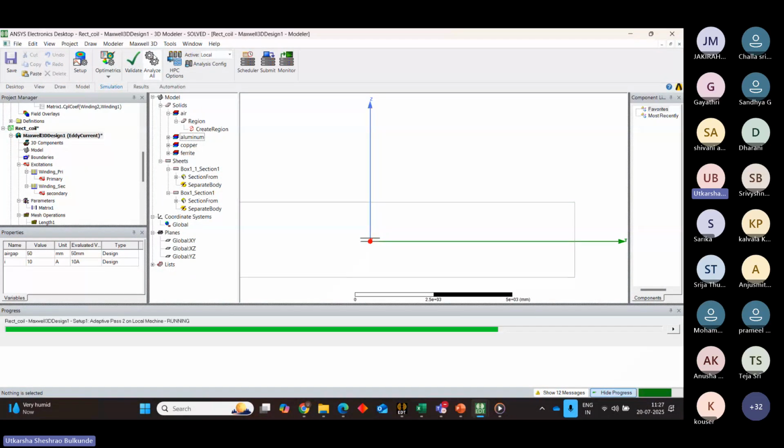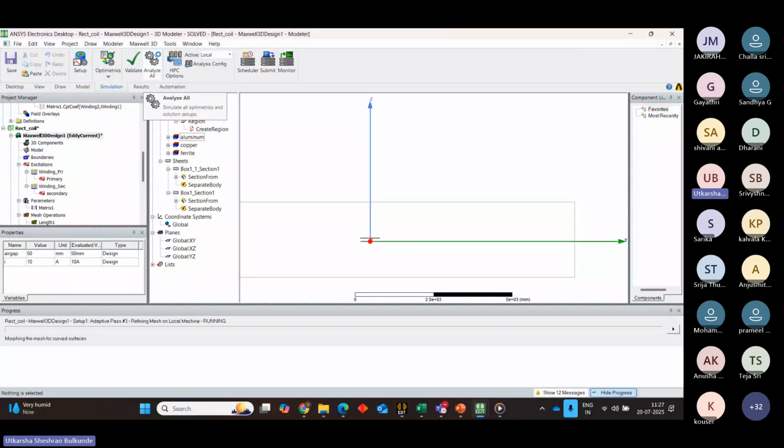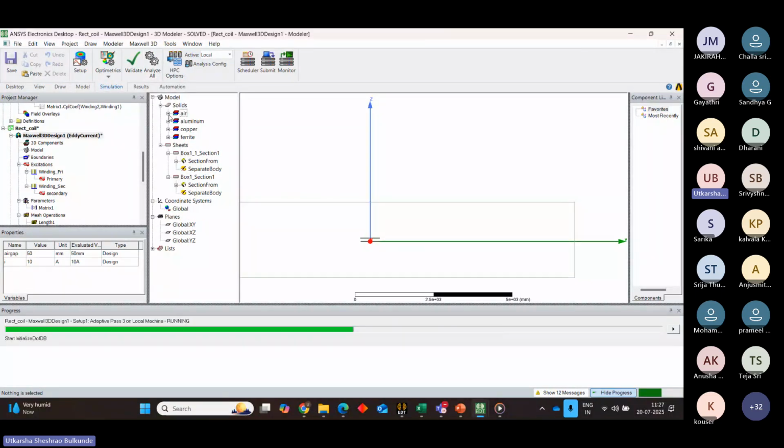So at least by my mistake, you have understood the importance of region. Even if you have done everything correctly, if you will not enclose your geometry under an environment, it will not give you proper results. It will not give you results at all. Okay, understood? Fine.